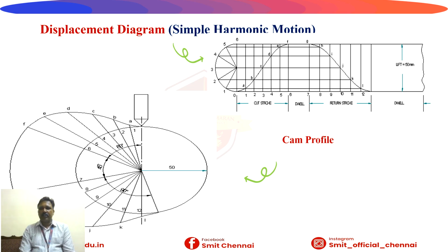The question itself gives it. So what is given here? The outstroke angle is given. We have to convert that into a scale in centimeters, and divide it into 6 equal parts, followed by the dwell area, and then the return stroke. To get a clear curve, we have to divide it into 6 equal parts.